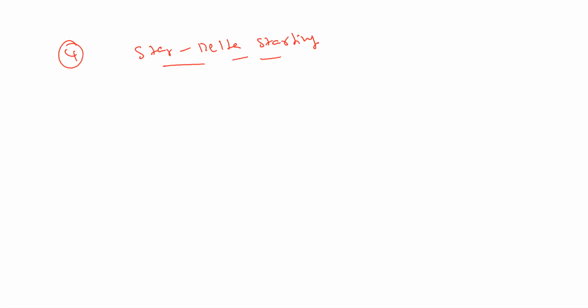Now, what we do is use a star delta starter. It's a kind of switching that we prefer. Initially, say your winding is delta connected. Normally the stator is delta connected. This is the 3-phase delta connected stator, and the voltage is applied here. This is the current we are interested in. Say ISC is the line current, which is √3 times the phase current for delta.